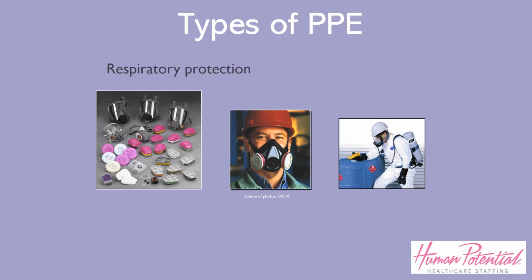Particulate respirators filter out dusts, fumes, and mists, are usually disposable dust masks or respirators with disposable filters, and must be replaced when they become discolored, damaged, or clogged. Examples are filtering facepiece or elastomeric respirators. There are chemical cartridge/gas mask respirators.